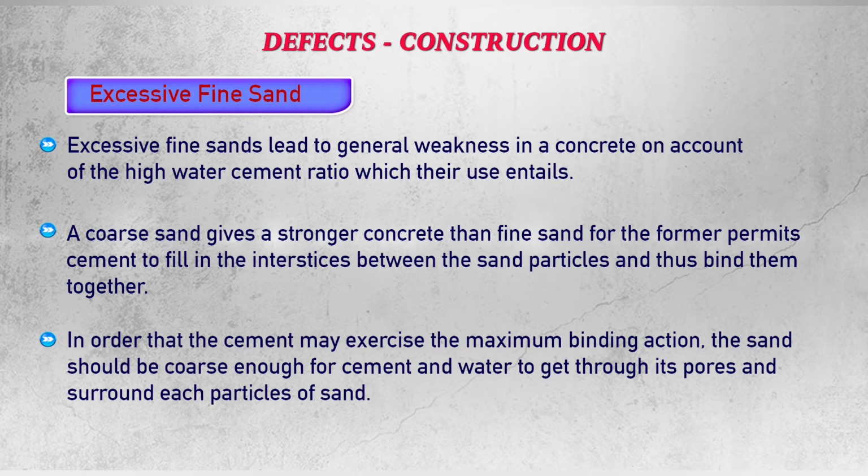In order that the cement may exercise the maximum binding action, the sand should be coarse enough for cement and water to get through its pores and surround each particle of sand. Because if coarse sand we are using, then cement water paste can go into the pores easily and it will form a layer around the particles of the sand.